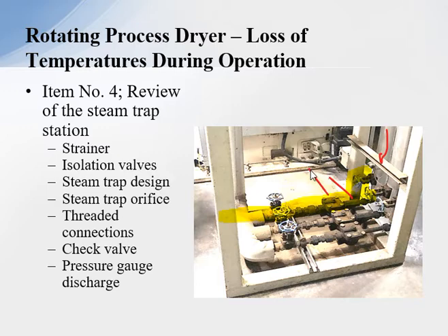The steam trap located here is the correct steam trap. It's a float and thermostatic design steam trap. However, on investigation, we found the steam trap does not have the correct orifice. The orifice in there was a small orifice, which was again reducing the capacity of the steam trap.